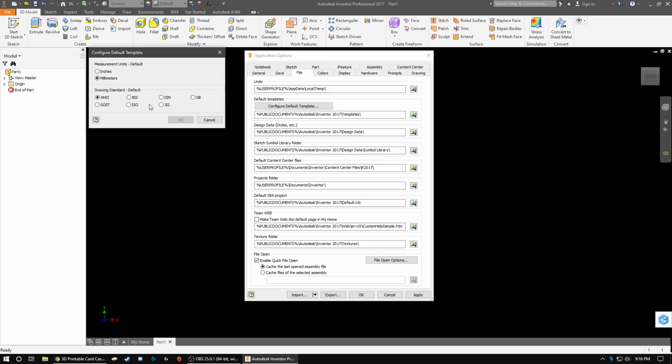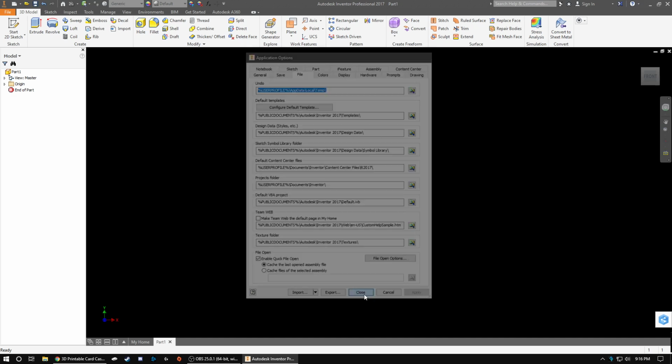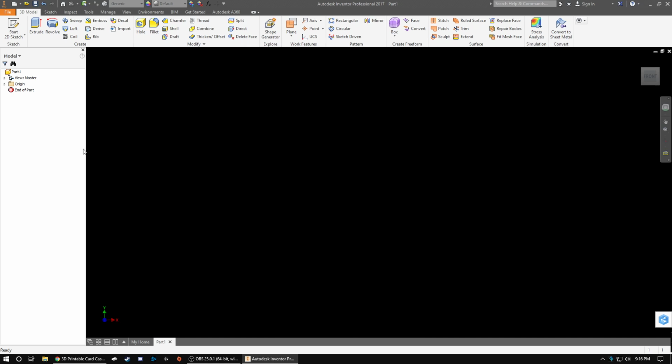It's a parametric drawing system, so the units are interchangeable. It knows the difference between the units, so you could make a line that's 5 inches and then extrude it up, which is make it solid, 4 millimeters. You can interchange them there; they mesh well together. Anyway, I'm going to keep mine on millimeters and then go into this. So this is already in millimeters.